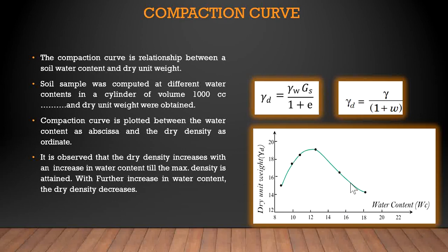Okay, so the state at the peak is said to be that of 100% compaction at the particular compactive effort. Okay, and the curve is usually of hyperbolic form when the points obtained from the test are smoothly joined. Okay, the wet density and the moisture content are required in order to calculate the dry density.